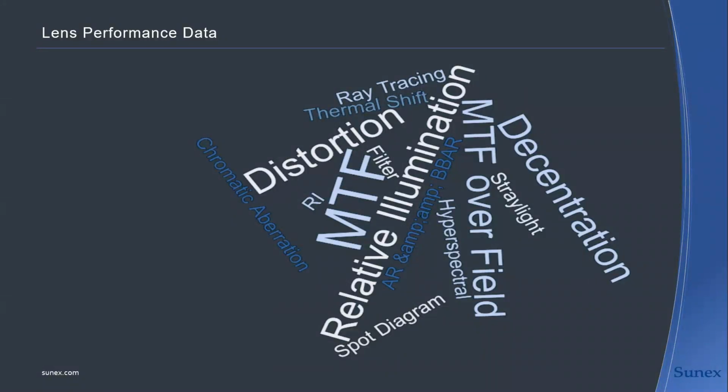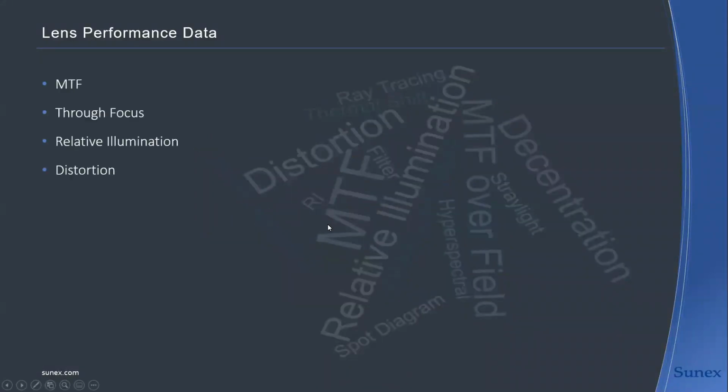But what we think is there's maybe 3 or 4 key things in the beginning: MTF, through focus, relative illumination, and distortion. They give you a very good idea if you compare them across 2 or 3 lenses, where you think, okay, I can maybe eliminate another possible lens and boil it down to 2. Because in the end, everybody also needs to be efficient with the time that we have, to help you towards the right selection.